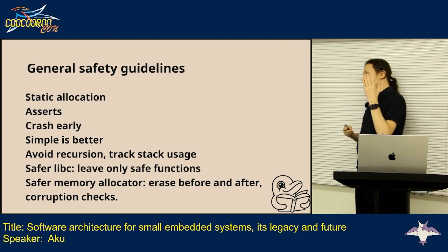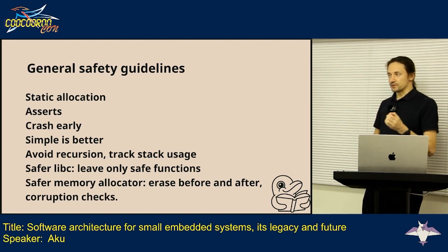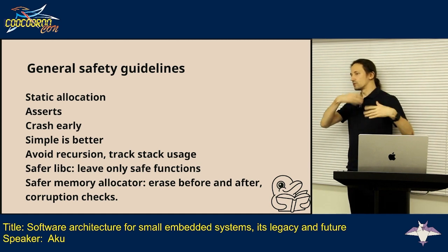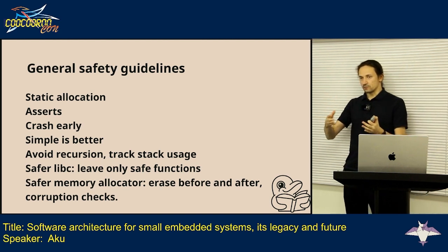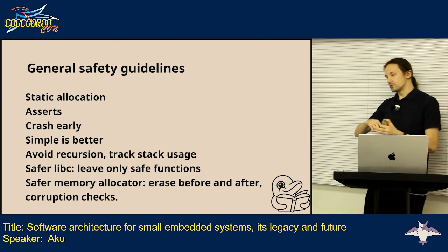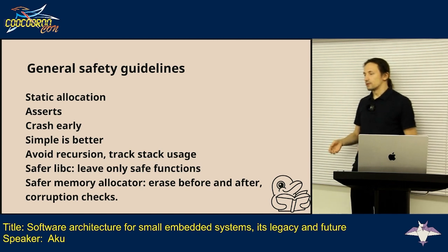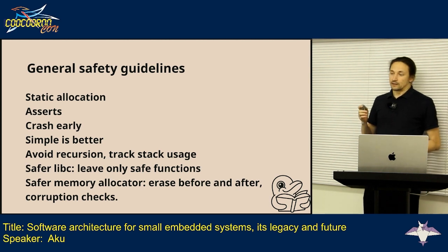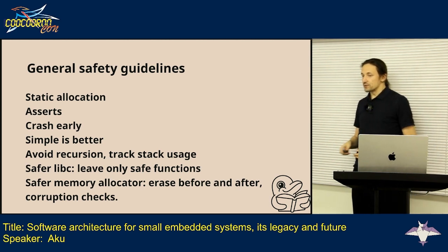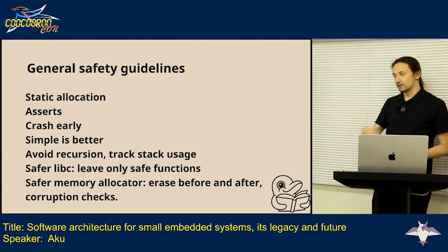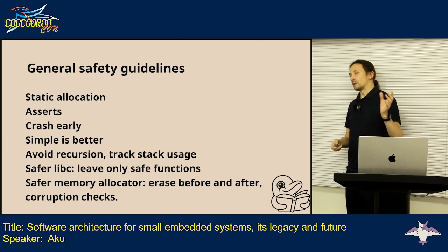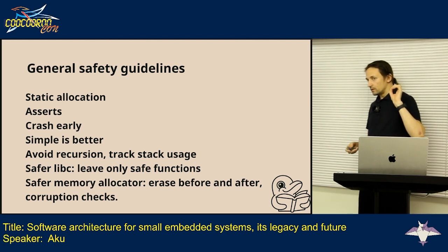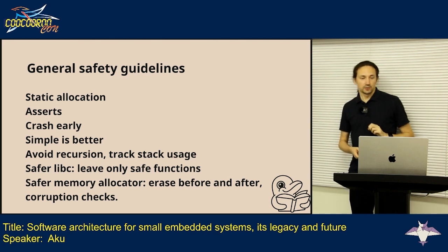The good example is string functions, the ones that just accept the string and then do something with it. So what if your data is damaged? In that case, if you don't have a limit, you will just continue processing. And with a microcontroller, no one will stop you because your address space is not limited. It makes sense to just remove those unsafe functions at link time, completely. So in case your developer tries to use them, he will be unable to link his executable.